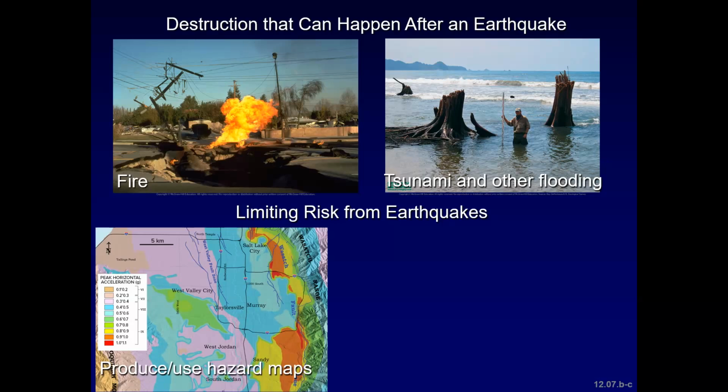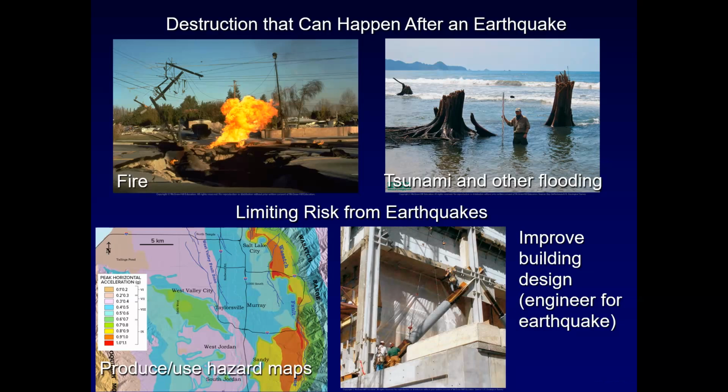We have an earthquake hazard map in the lower left showing zones of potential damage. This is the Wasatch Fault Zone in Utah. And our highest damage risk is shown in red near the active normal fault zone system. If buildings are modified or were modified in this area, shaking damage to structures can be mitigated. So if possible, you want to improve building design. That's going to cost money, but this is a defense against a natural hazard such as an earthquake.